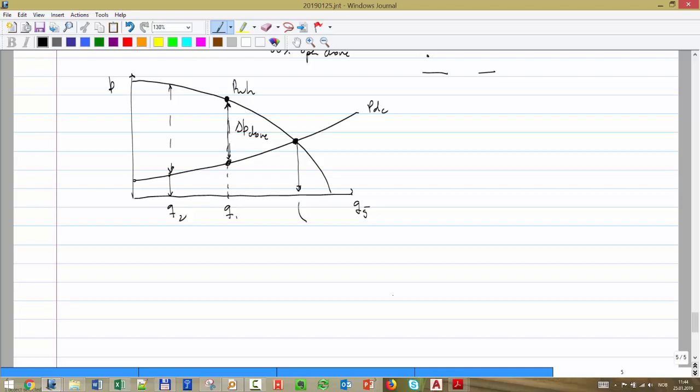In this case now, I have my production potential. But I can produce less than that, no problem, by choking. I just find a way, but I should be able to produce any rate below that. You see, now the potential is not coming simply from substituting minimum pressure in the IPR equation, not from a reservoir simulator, but now it's coming by taking into account the whole system, the whole intersection, all the system of equations.